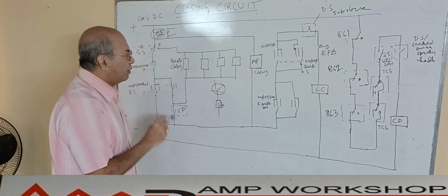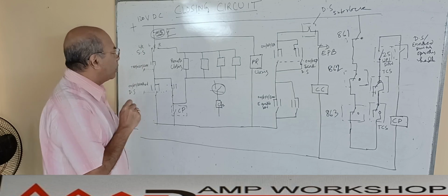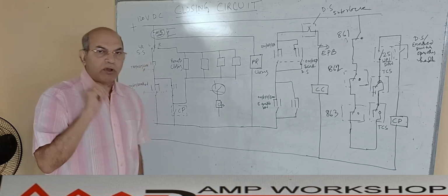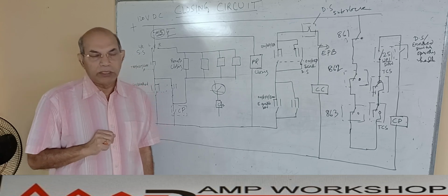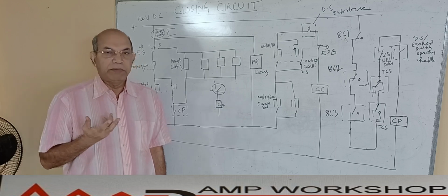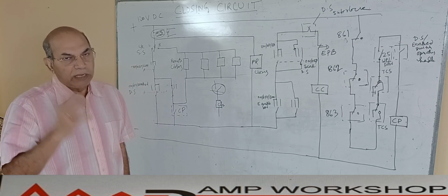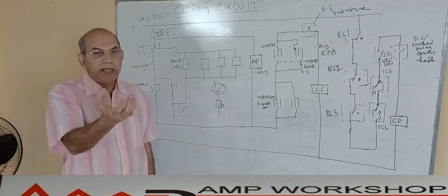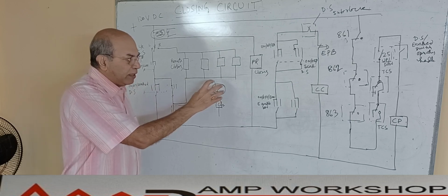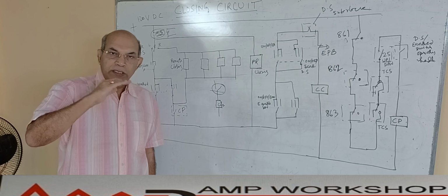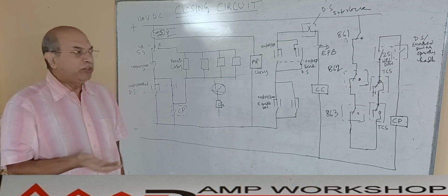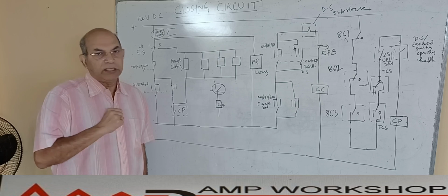Now this isolator, now here is a glimpse. Now when I am going to close the switchgear locally, mainly in two occasions we close the breaker locally. One position: if there is a breaker problem, we need to test the breaker. So during testing of the breaker, what we do, we keep the isolator open or we take the breaker in the test position, so the breaker is not in service position. In case of fixed type design, when the isolator is there, we take the isolator to the disconnected position, means the isolator is off. Isolator off position we take when we want to test the circuit breaker.